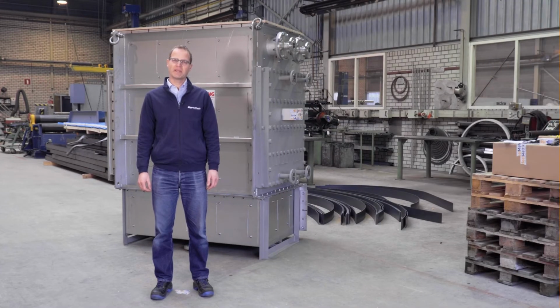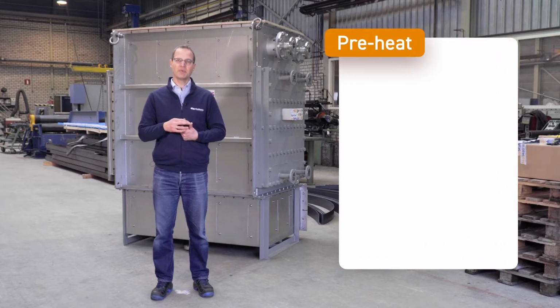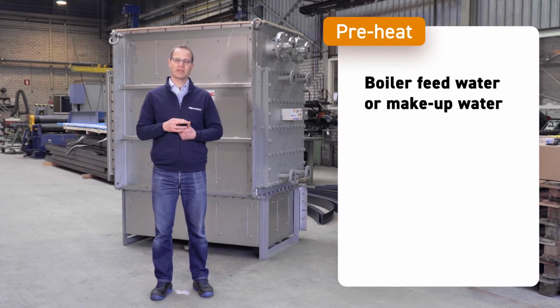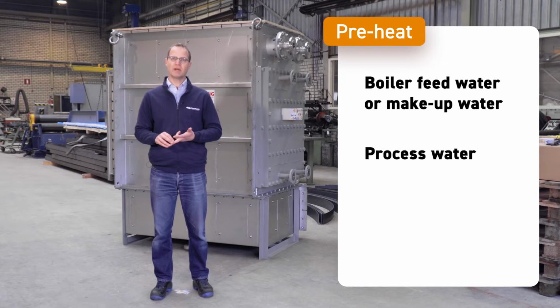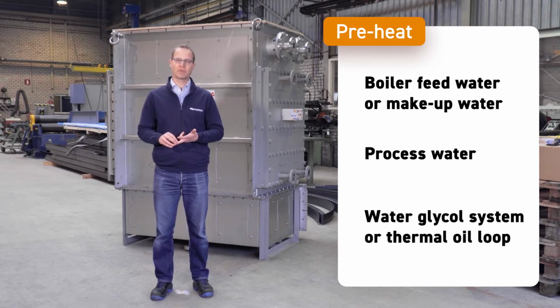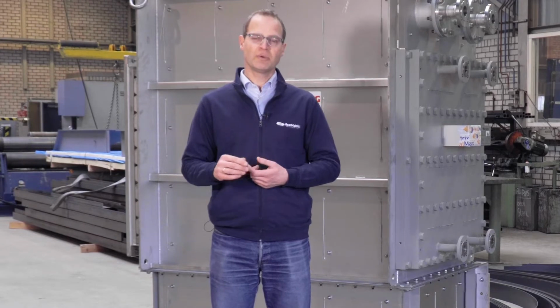In general, the heat recovered by the economizer can be used in three different ways. It can be used to preheat the boiler feed water or makeup water in the steam boiler. It can be used to preheat process water for processes outside the boiler. Or it can be used to heat up a water glycol system or a thermal oil loop to use the heat somewhere else.